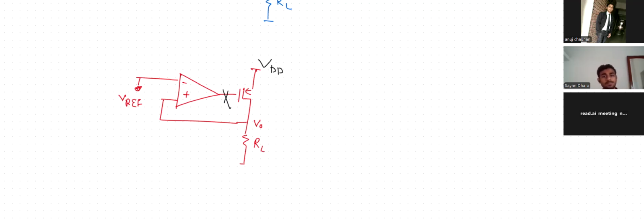Okay, you need to calculate loop gain for this circuit. What I can do for loop gain is short circuit, I mean ground, the input here. We can ground this, and this VDD also, and for loop gain we will apply a VTest here and find a VF, or how much it is actually getting amplified.